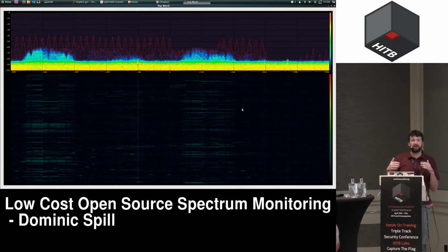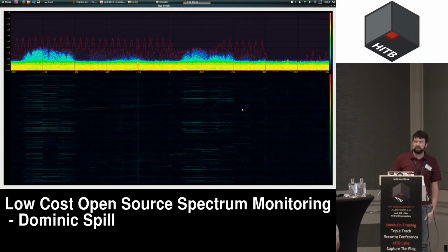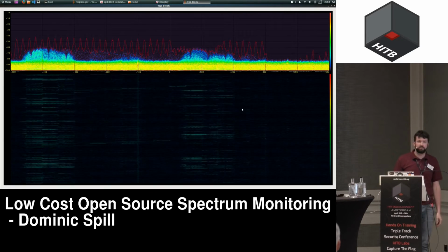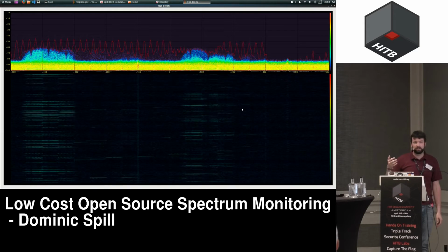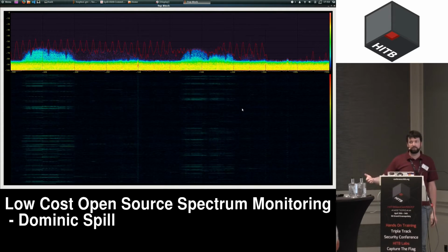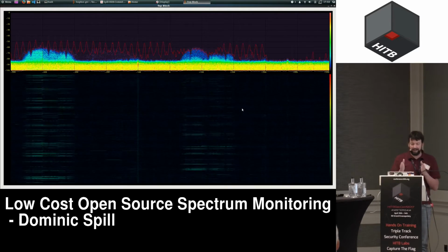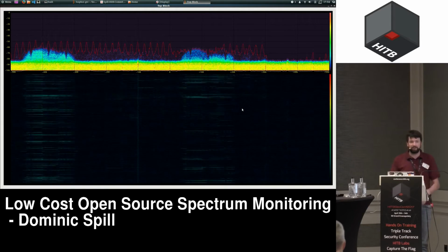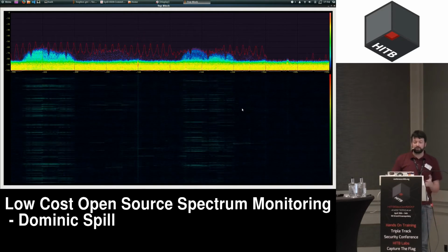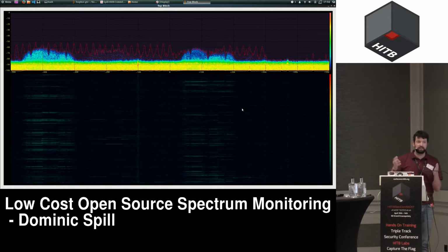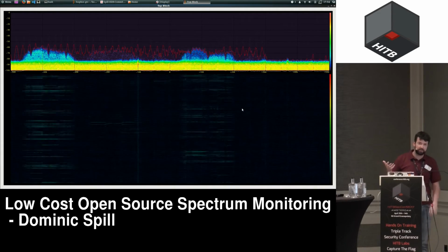But those bursts are very quick, and they're transient unless you're looking in the right place. I mean, 10 years ago when I was trying to build our first software-defined radio implementation for Bluetooth, I had to point at, at the time, an 8 megahertz wide chunk of bandwidth and just hope that Bluetooth strolled past at some point. Whereas with this, I'm able to go and look at where it is in the spectrum. And for Bluetooth, it's all over the place, so it's probably not such a big deal.